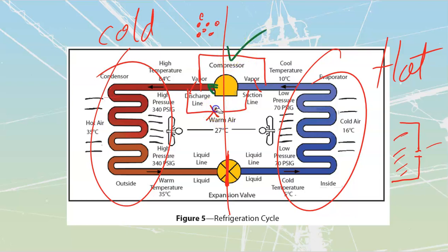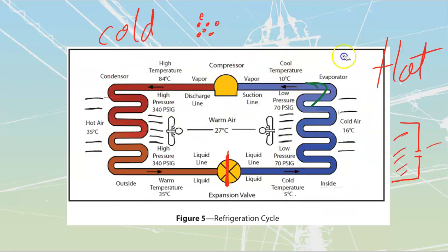But if I were to close those valves and open these valves up top over here, so we'll open that valve, and then we will close this valve and close that valve. What I would see is, once again, because my pump is pumping out of there, now my pump would be pushing that through in this direction, and I would be able to push all the way through from here. It would then be able to go back in. So my pump can still run in the same direction. It's just a changing of the valves, but I can interchange which side is going to be hot and which side is going to be cold.